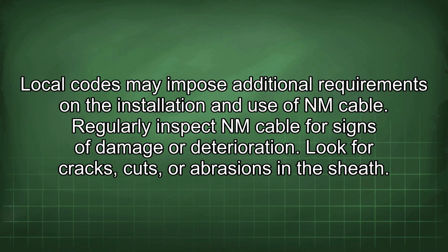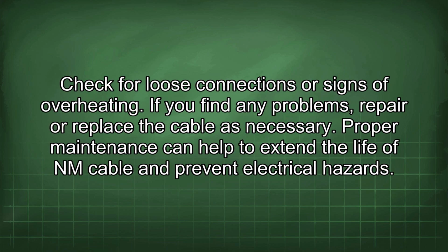Regularly inspect NM cable for signs of damage or deterioration. Look for cracks, cuts, or abrasions in the sheath. Check for loose connections or signs of overheating. If you find any problems, repair or replace the cable as necessary. Proper maintenance can help to extend the life of NM cable and prevent electrical hazards.